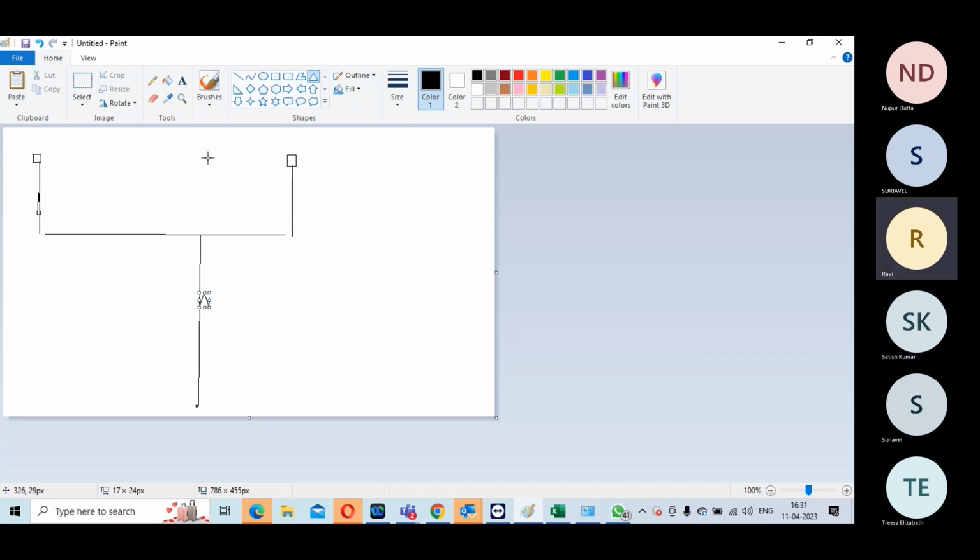Yeah, see, how I would actually suggest is, first you build this route. You build this path. Don't touch it. If possible, even the stem. If possible, between these two muxes, you can build whatever in the tree. Balance it. This clock tree, that's what you have to understand from a clock design. Clock tree diagram, right? You build this and then you allow the tool to construct the clock tree from these points. You go and balance. This is easy for you to build manually.